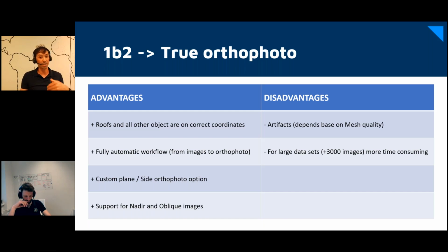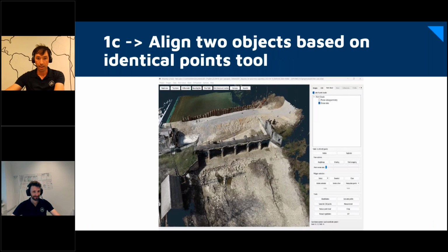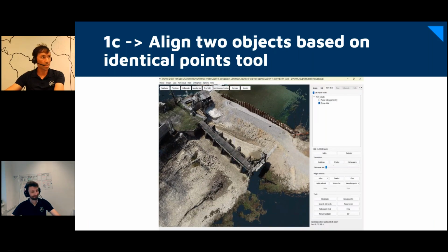Another disadvantage is that the algorithm for textured 3D models and also for mesh calculation is much harder, so it's a more advanced algorithm. Definitely for enormous, huge areas, the calculation will take longer, and maybe you will need to split super big projects into two areas. We improved this quite a lot, as Mattia already explained, but definitely the traditional orthophoto is much simpler. Cool. This was from my part.